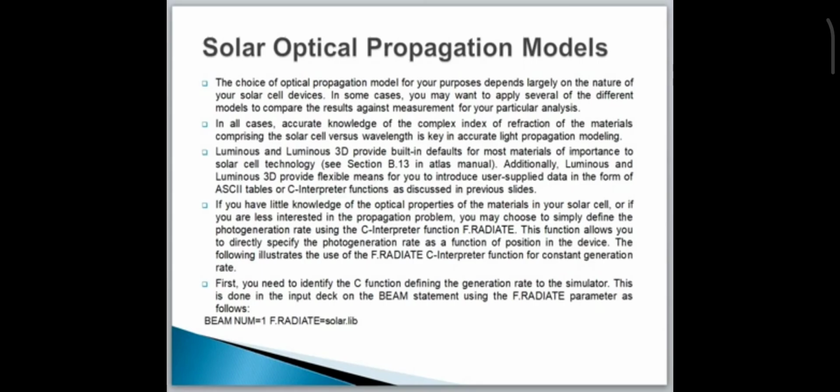If you define the ray in this manner, F.RADIATE solar library, you don't need to define any NK file in the material statement. You can see in the Atlas examples, most of the experiments are using the F.RADIATE syntax parameter to define the beam spectra.